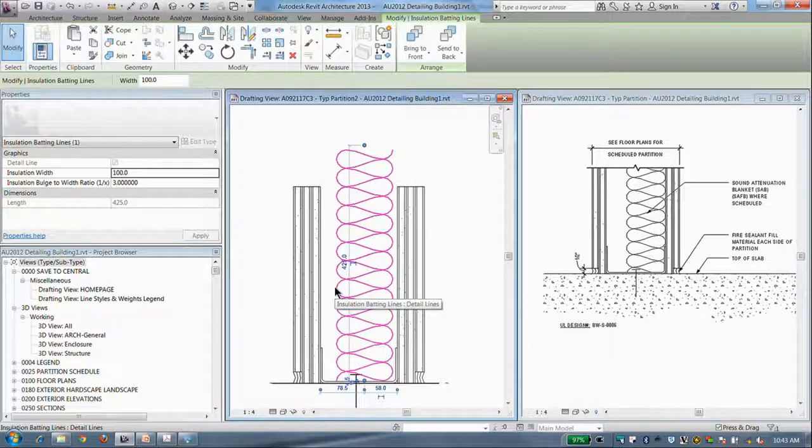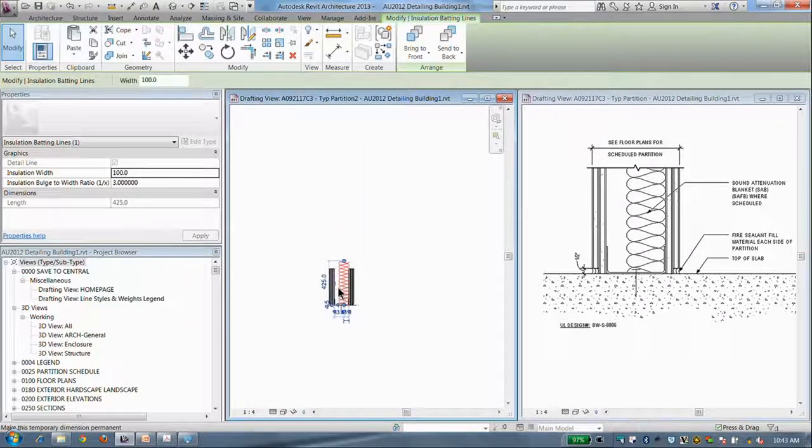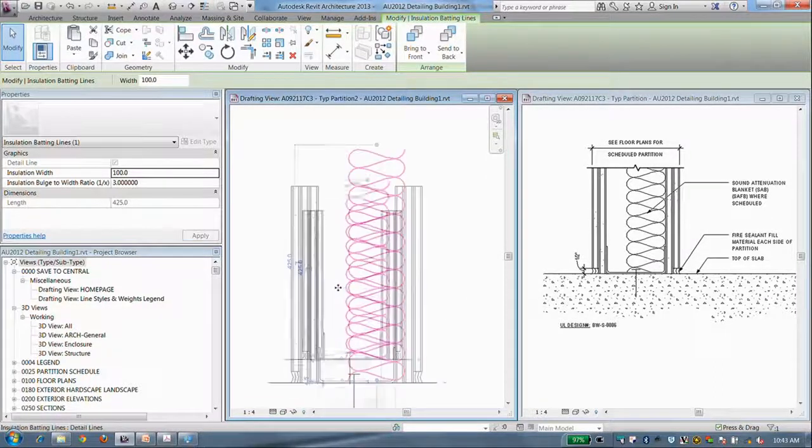And when I shift it over, so using the move tool, I'm going to use the arrow keys on the keyboard. Those are the nudge keys, and what those do is they move the item over. If I remember correctly, it's about 2 millimeters on screen, so it's actually related to how close in you're zoomed to your view. If you zoom way out, it's moving 2 millimeters at that level. So the farther you're out, the more it's actually moving in real life units.